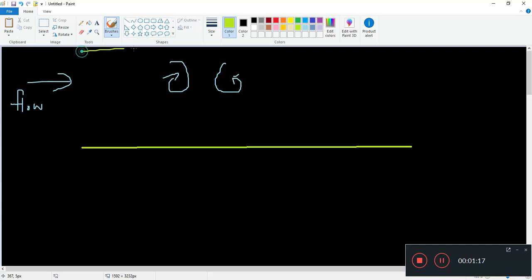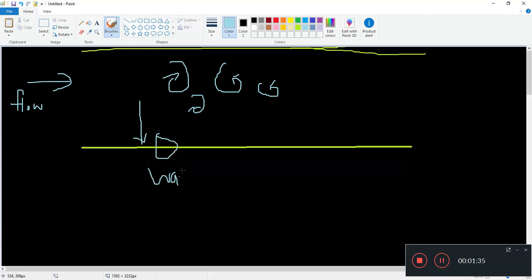Let's say this is a pipe, and in the center of the pipe there is turbulence going on. Now, the thing is, as you go very close to the wall region, so let's zoom in here, you have this thing called the wall region. In the wall region, you can imagine the turbulence will have to start to die down somewhere, because there isn't enough space for this turbulence to keep swirling and swishing around.